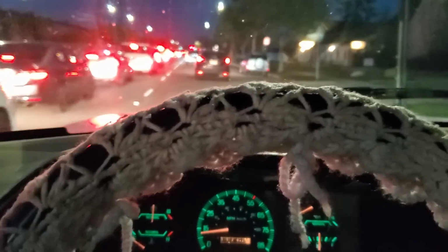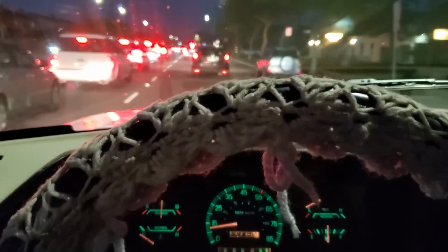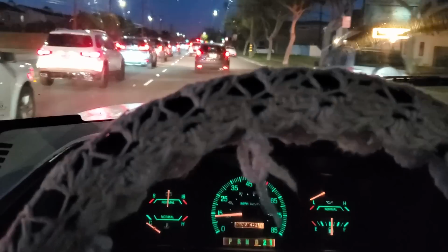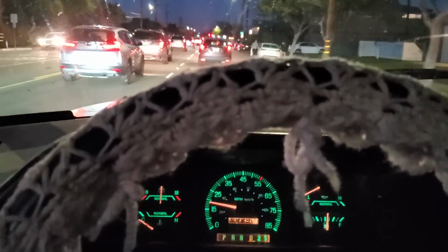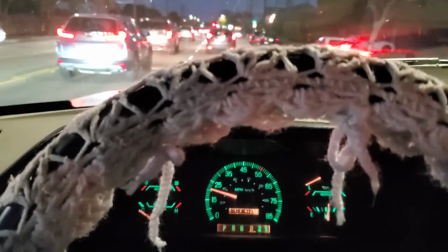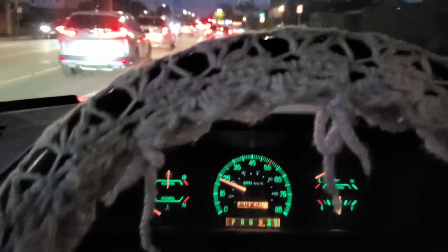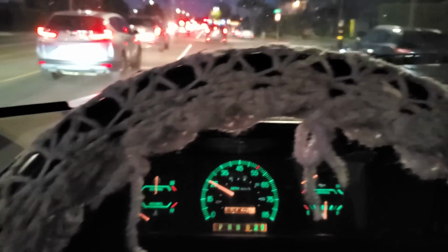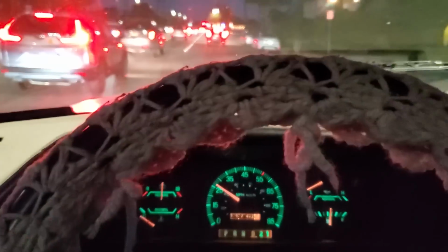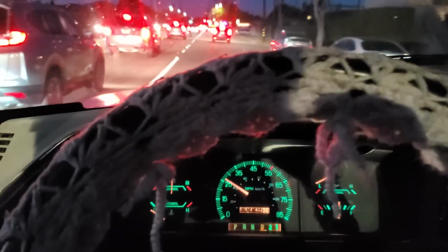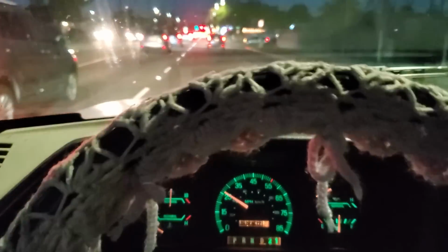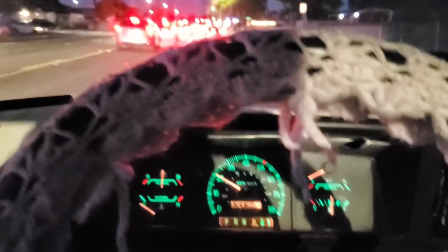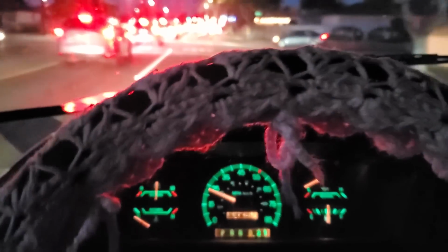That also explains why the NOx limits, the oxides of nitrogen limits, were so much higher than I thought, because the state allows a much higher NOx on heavy-duty vehicles, because the EGR really doesn't start to open on these until you're under a really heavy load. So it seems to be running pretty damn good.